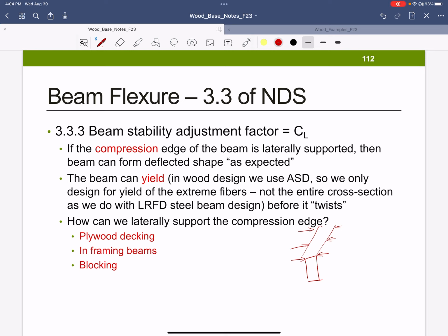Our stresses that are in these tables are the yield stress, okay? So it's the part where if I'm looking at a stress strain curve, I am looking at the part where it starts to go nonlinear, the peak of the linear, and the yield stress. So those are the stresses that we are using in here.